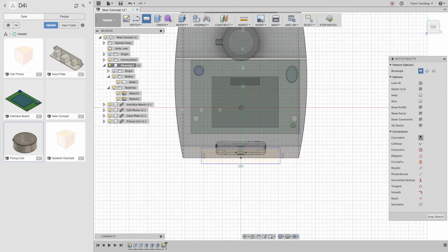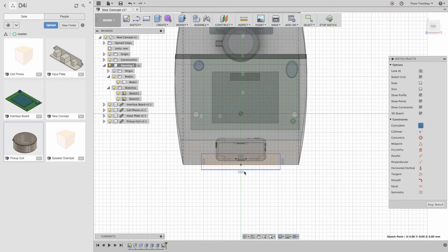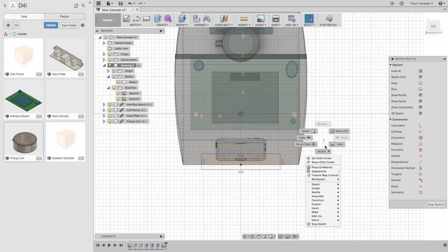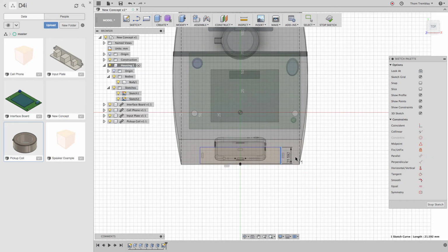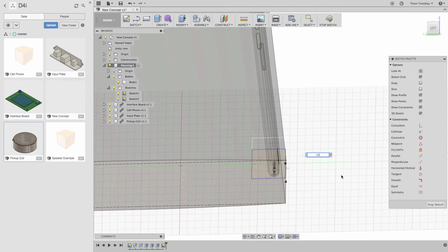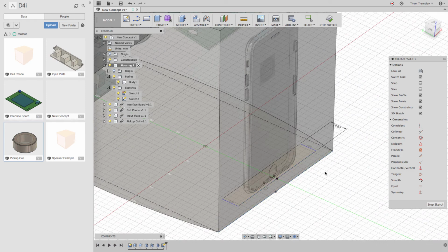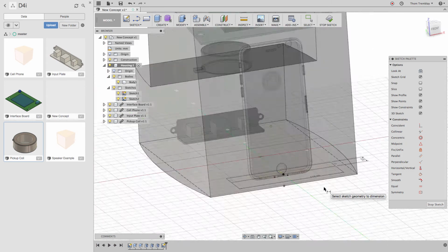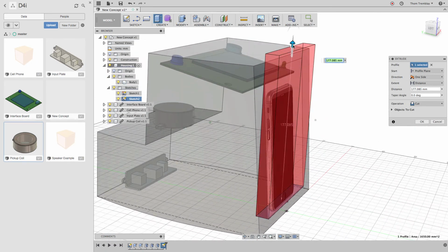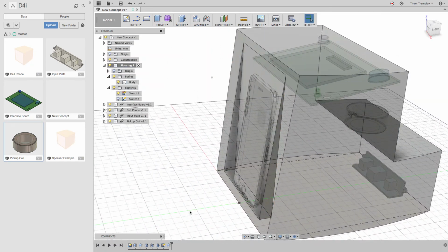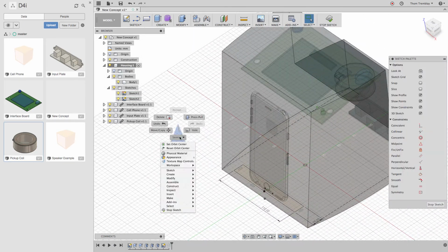I want to make sure that this is compatible with a few sizes, so I'll include some sketch geometry, lock in the sketch to the middle, and then I can apply some dimensions. Or I can reference other geometry that's already in the part to make sure things are aligned. When I extrude this up, I see that it's just a little short of where I want it. But there's no need to get rid of the feature.